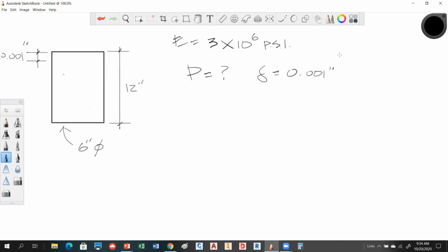So this is really cool now because in the last section we were just looking at, okay, we can calculate stress as long as we know P and the cross-sectional area. And we can calculate strain very effectively because we know the measured values. We get the original distance and we got the deformation. But now we're able to solve things like, well, what force is causing this? So let's list everything we got. This is concrete. We need P. We know that the deformation is given, and the original L value, original distance, is 12. That allows me to calculate a strain, right? We also know that the area is calculable.